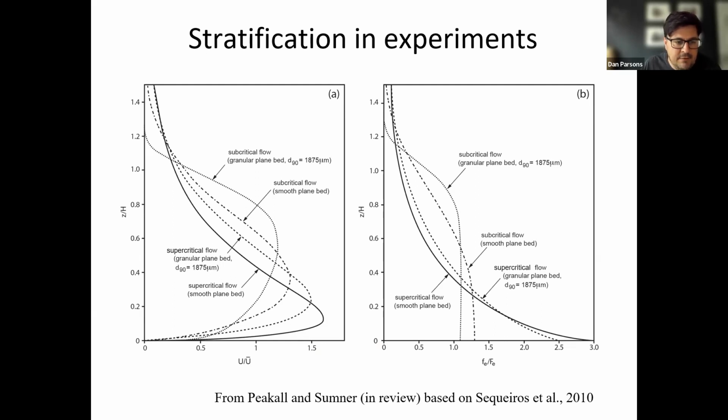And what you can see is a very simple model we developed that looked at where the velocity maximums were. So there's a series here. You can see the velocity maximum very close to the bed, this is the one close to the bed. A river channel would have a normal profile that you just see increasing velocity up towards the surface. But these are just a range of different gravity currents with different amounts of stratification, and that stratification controls, or is controlled by, of course, where the velocity maximum occurs.